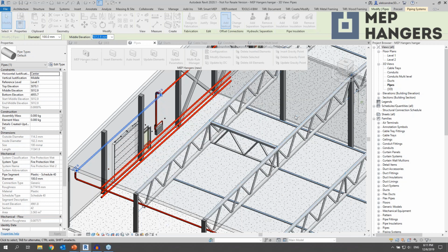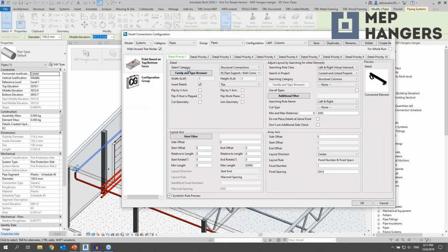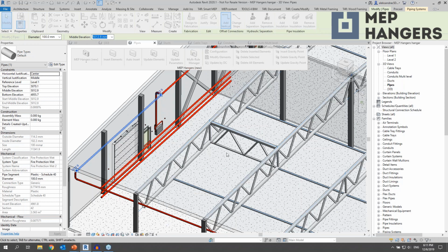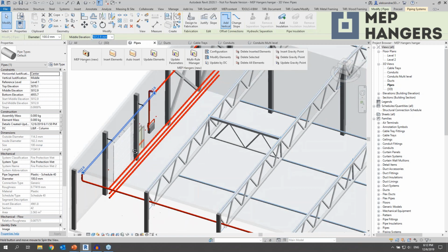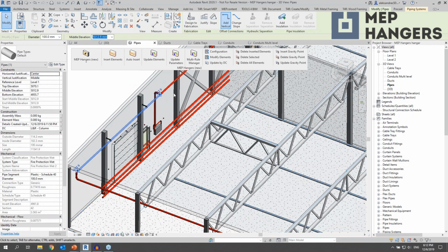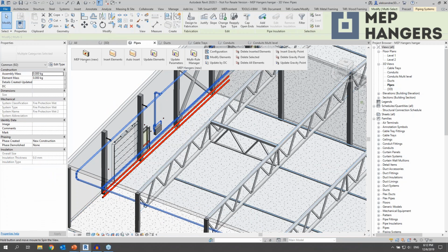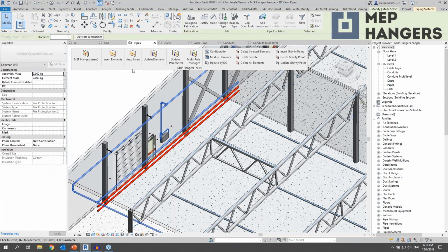If you want to check the rules, you can click on Edit. That will show what rules will be applied: again, which hanger, to what connected, how distributed. So in this case, it's this hanger. We can click OK and Insert Details. That will connect hangers to the columns. If you want, you can select all the system at once, which is connected, and do the same procedure.